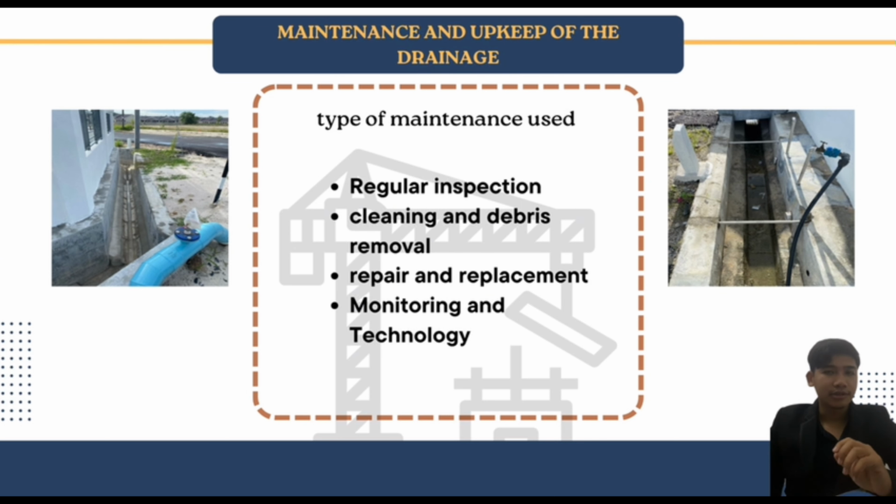Next is the cleaning and debris removal. This maintenance should be done frequently. This is to prevent the drainage from clogging. Next is the repair and replacement. Since this project is quite old, repairing any crack and damage can prevent the drainage from leaks and water infiltration.